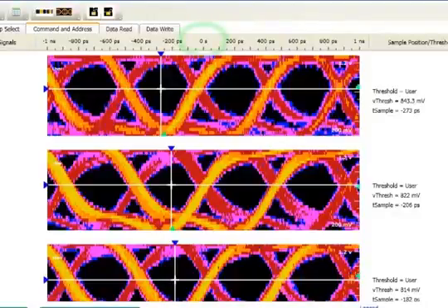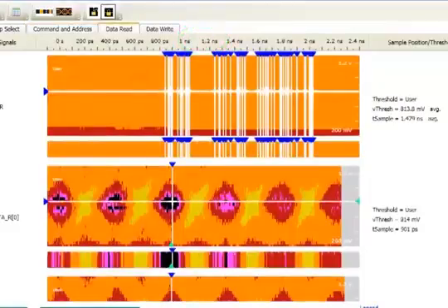All scans are relative to the 0 point, which is the clock edge that is clocking the logic analyzer. For DDR3 measurements, 0 equates to CK0 rising and falling edges. That is why on the address and command lines, we do see activity relative to the falling edge. Next, we'll move to the read data group.